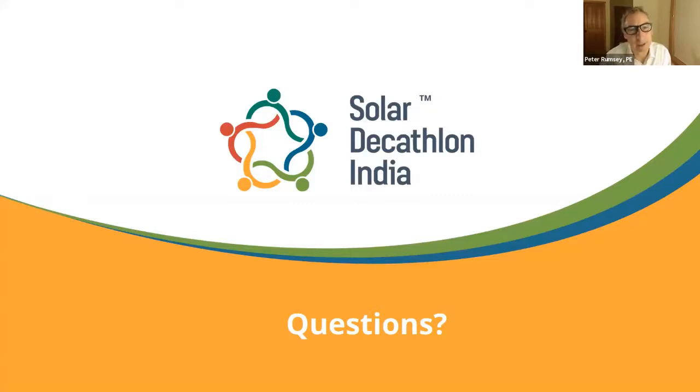So ASHRAE is the go-to to get the textbooks and the data and all that, but for the higher level, getting introduced to the concepts, I actually think that Wikipedia articles are good resources to get started. But definitely as you get into it, ASHRAE is the best place. And they have a textbook, in essence a teaching book, called The Principles of HVAC. And then they have the reference book, which is called the Handbook. And the one you want to look at for load calculations is called the Fundamentals.